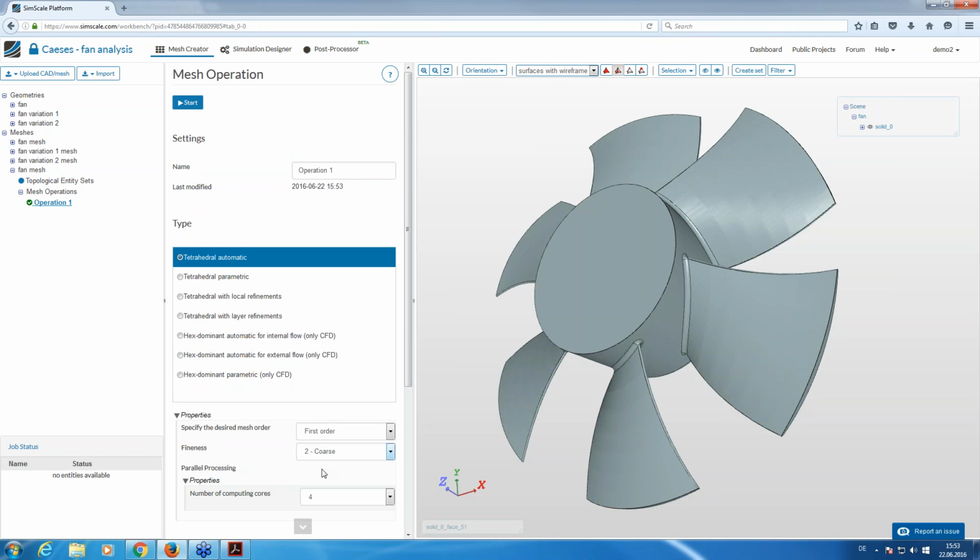You always want to start with a very coarse mesh simply to see if your setup is the one you want, and then you refine your mesh and see if the solution for all of those different meshes converges to a constant value. Then you know, okay, this is the mesh I want to use for my parameter studies or similar things.